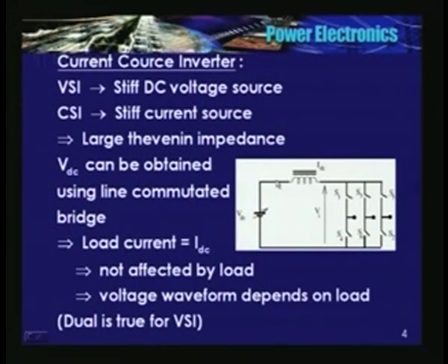This sort of operation we had seen in three-phase AC to DC conversion. Almost the same thing. At any given time, one device in the upper half and one in the lower half is conducting. Because of the same principle, there also we had a load which is equivalent to a current source type.